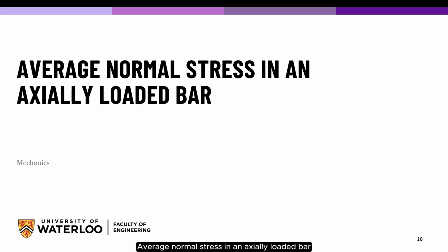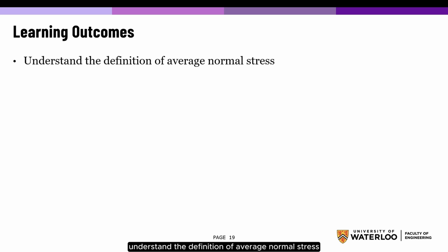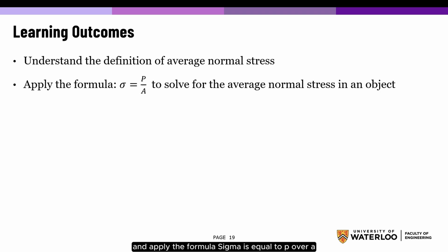Average normal stress in an axially loaded bar. Let's look at some of the learning outcomes. Understand the definition of average normal stress and apply the formula sigma is equal to P over A to solve for the average normal stress in an object.